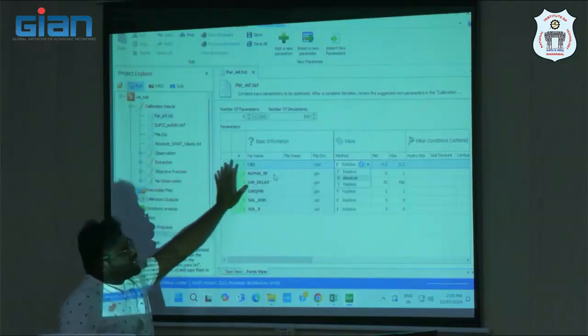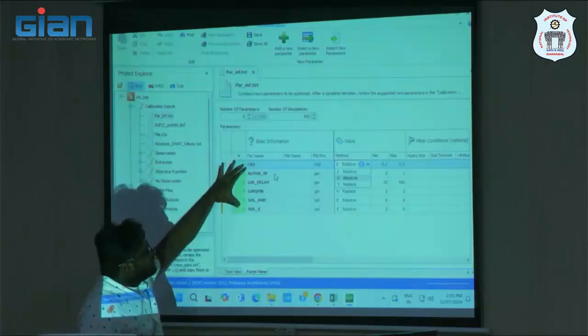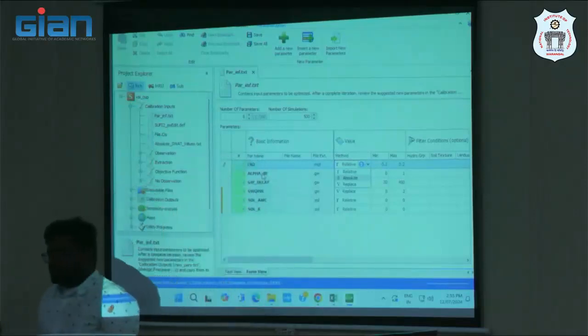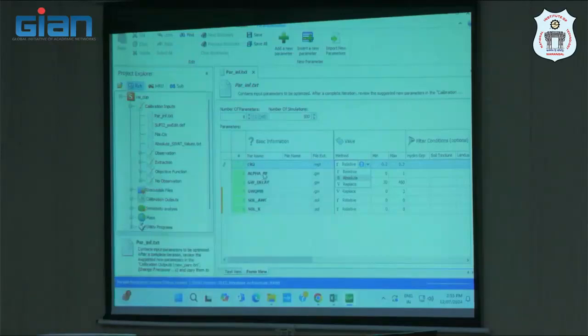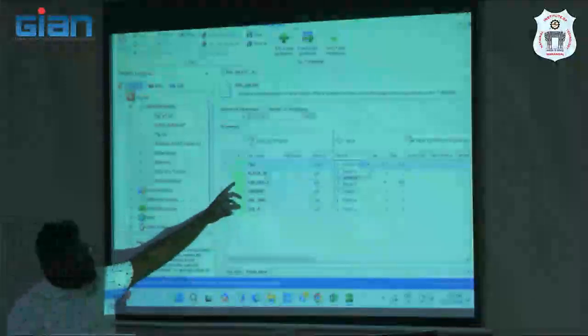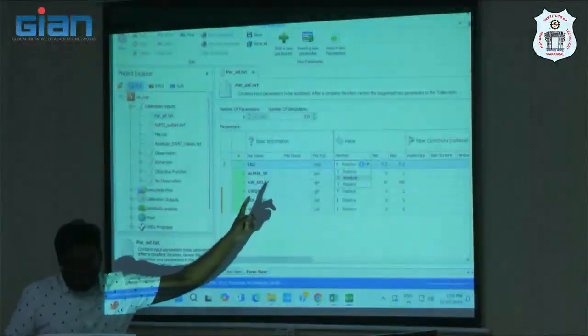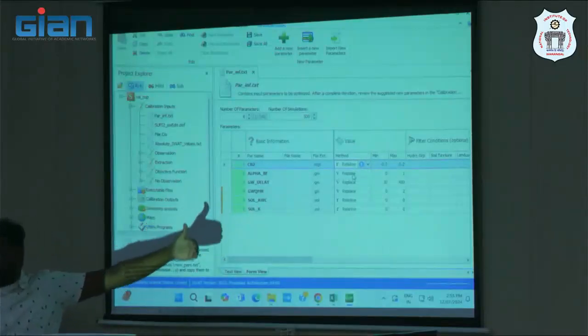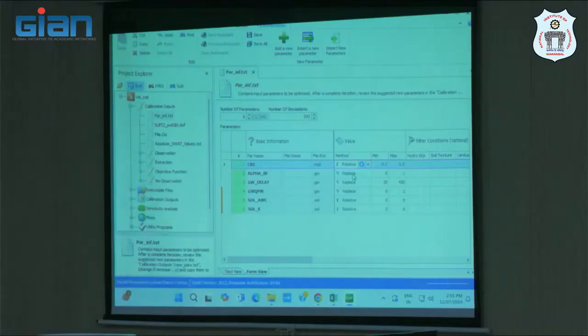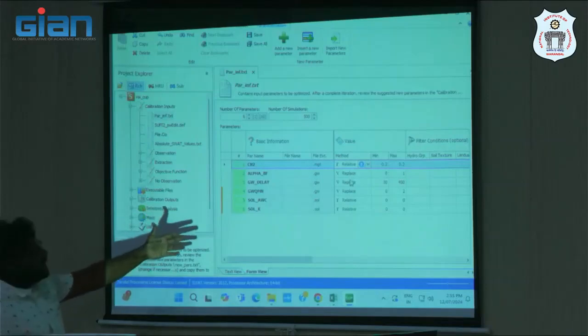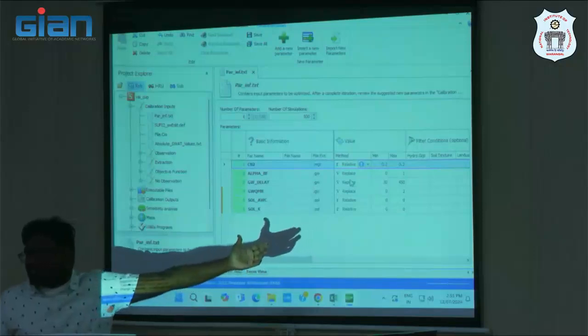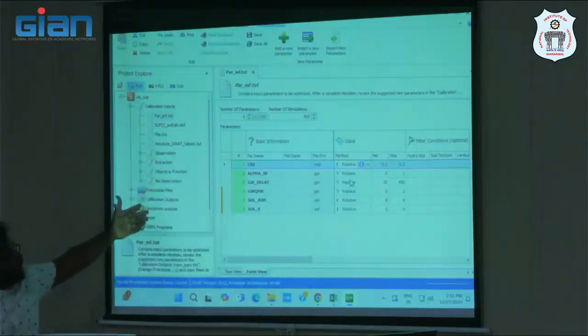So, as per the literature review, as we have seen, SWAT was not able to capture all the groundwater spatial variations. So SWAT assumes that throughout the subbasin, groundwater parameters are the same. Okay. So this alpha BF is base flow, and it is also a groundwater parameter. So all the groundwater parameters are not changing with respect to subbasin. So you can use either additive or replace. So choose the replace method. For groundwater delay also choose the replace method. Just change that method. Okay.